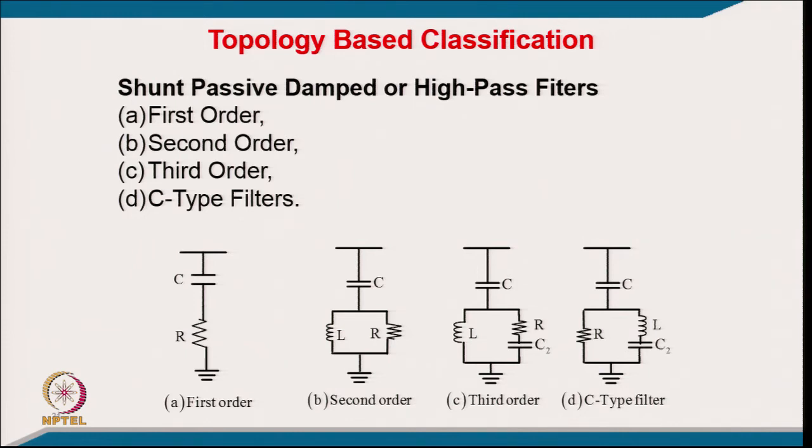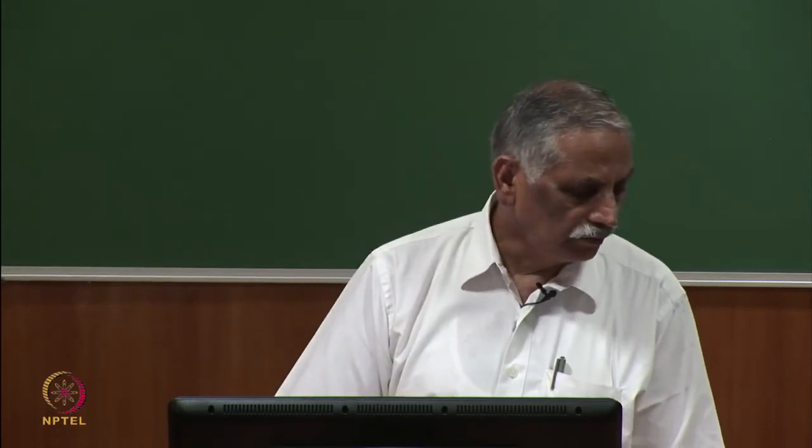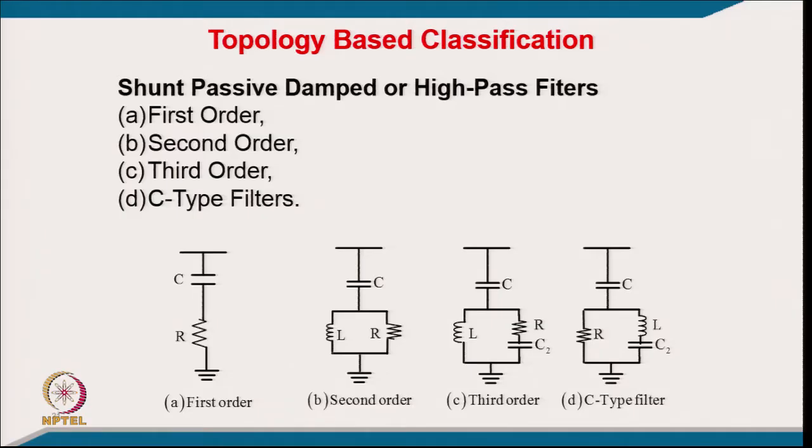So, you can see the resistance is decided accordingly, and the impedance for all higher order harmonics is equivalent to R. But at the fundamental frequency, the C has a very large impedance. So, it will not have any fundamental frequency current, and losses at the fundamental frequency will also be quite low in this case, because it is not drawing a very large current. So, it will not put any kind of reactive power burden on the system.